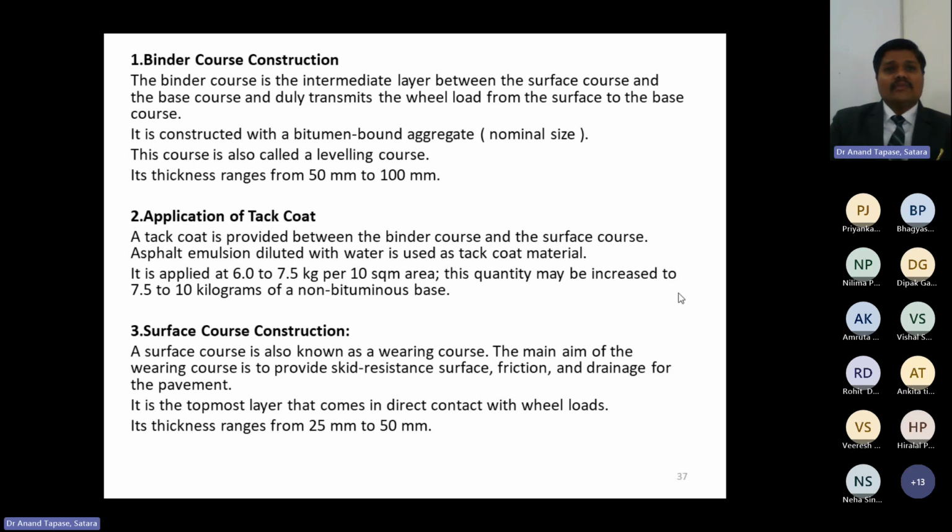For the natural subgrade, to increase its CBR value, we should have an artificial subgrade. IRC has proposed a thickness of around 500 above the natural subgrade, made artificially, so that the CBR value is increased. In between there are tack coats and prime coats at various intervals. That is not part of today's discussion, but it is part of the construction activity carried out while constructing a pavement.